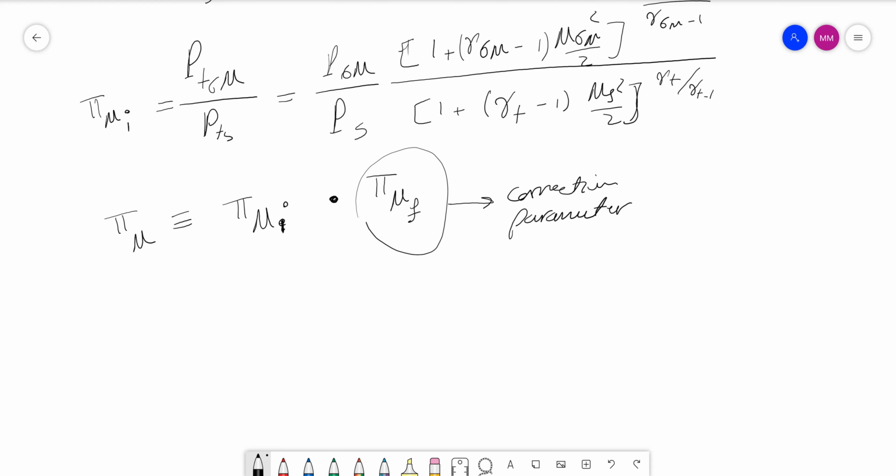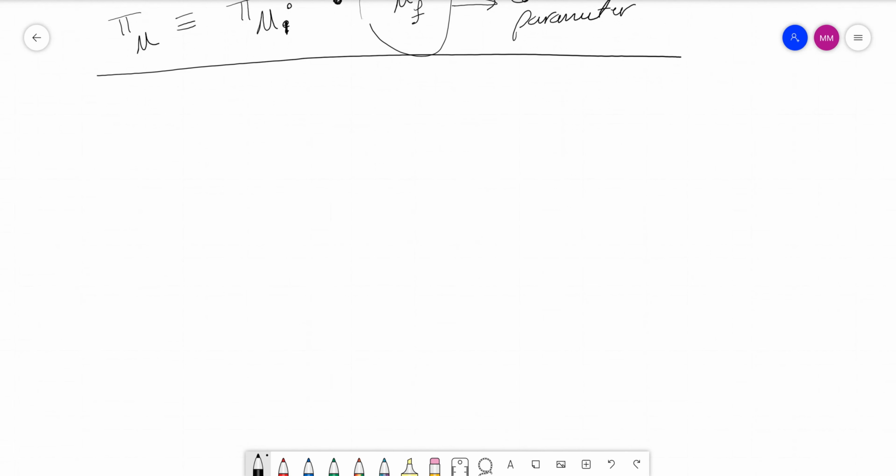When you have the information of the mixer, you go to the afterburner, you calculate the afterburner properties, then you go to the nozzle and you calculate the exit velocities, and you can eventually end up finding the thermal efficiency, propulsive efficiency, TSFC, specific thrust and so on and so forth, right? I will probably upload another recording of this lecture, and we'll go over one of the examples of the book as far as this type of turbofan engine is concerned. But that's it for the discussion.